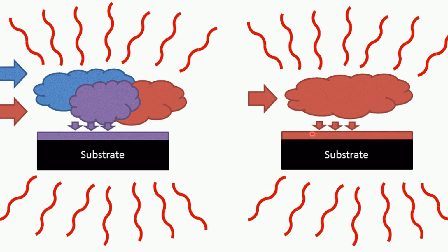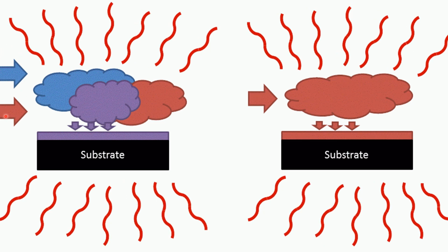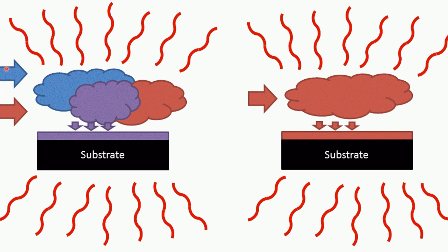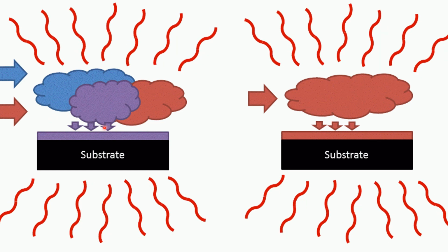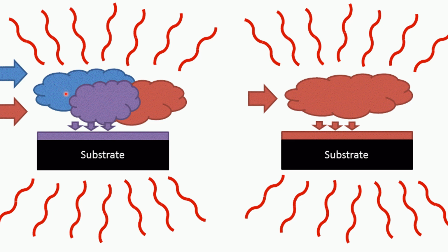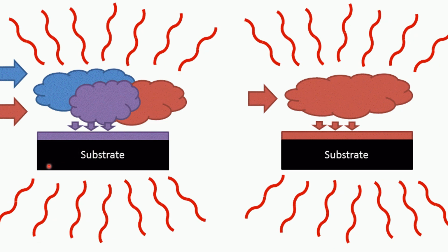Usually in general CVD processes you use a wide range of precursor materials. You introduce multi-component precursor material at the same time and they react on the surface of the substrate, which is hot, and the chemical precursors, which are introduced onto the surface of the substrate by a carrier gas, react onto the surface of the substrate and at the end they get condensed and converted into a thin film.